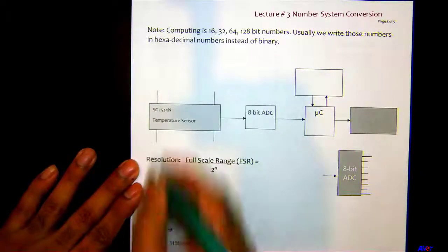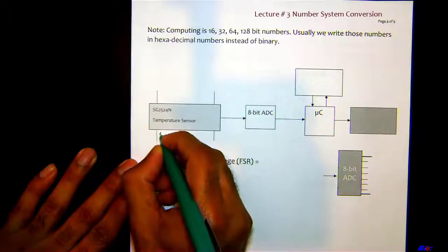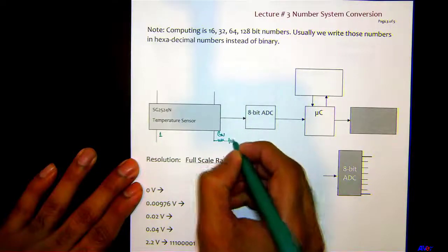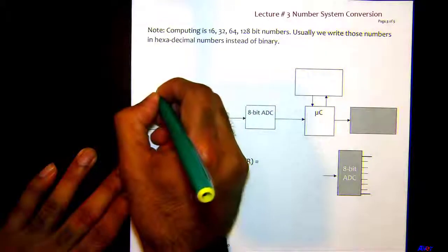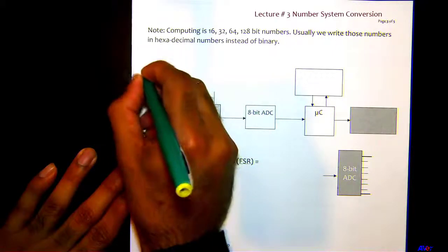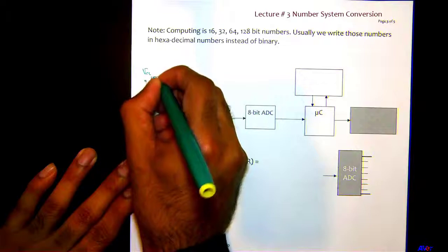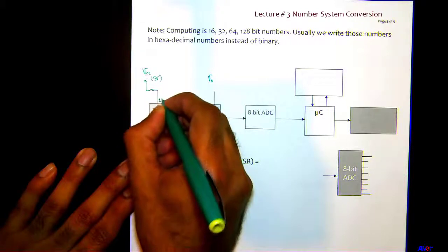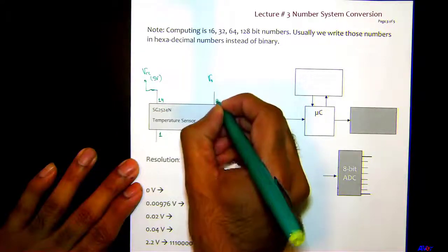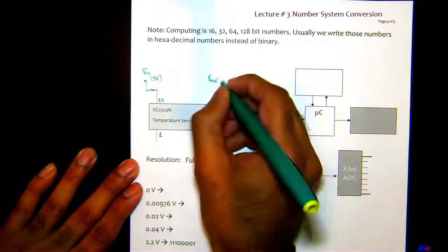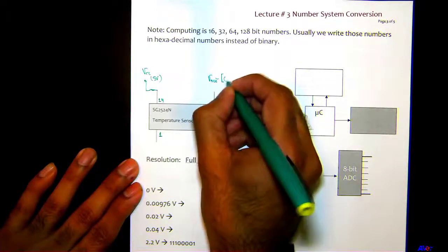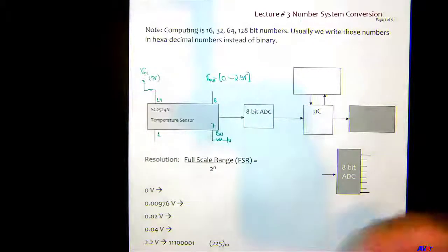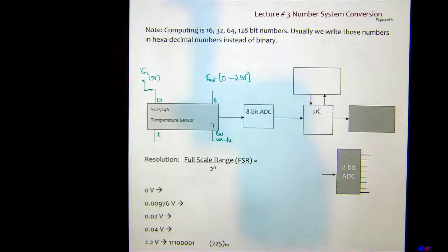Say you have this temperature sensor chip. Again, this is pin number 1. This is your ground, so it's connected to ground. And then this is your VCC right here. Say this is 5 volt or something, and this is your V out right here. This is pin number 14, 7, this is 8, V out. This is the V out, which is going to be between 0 and 2.5 volt. And if we have the data sheet, we can find out if the V out is 2.1 volt, how much would be the temperature, and so on.